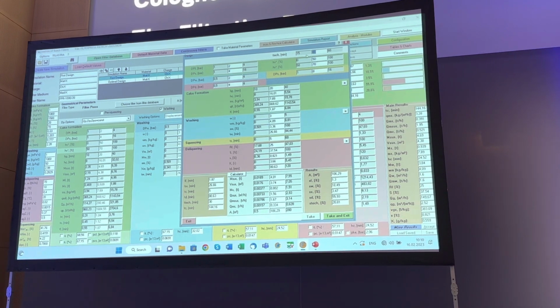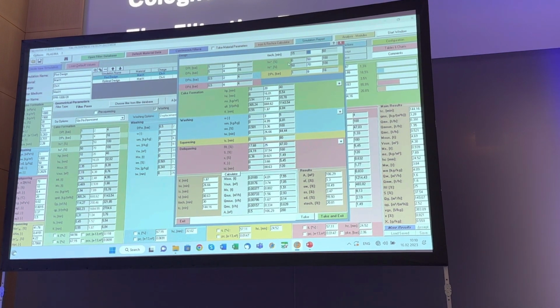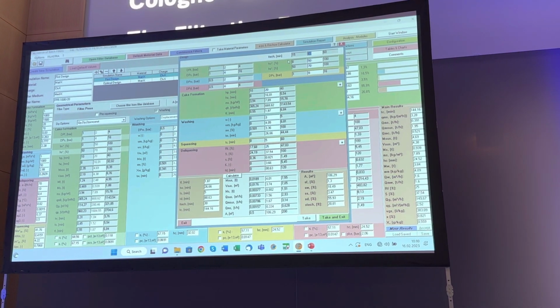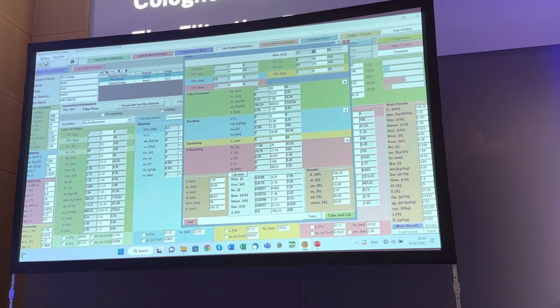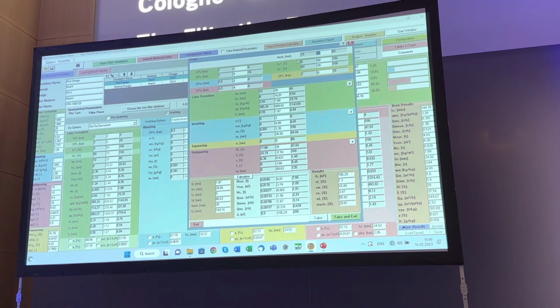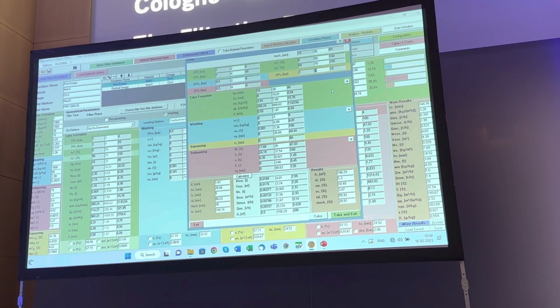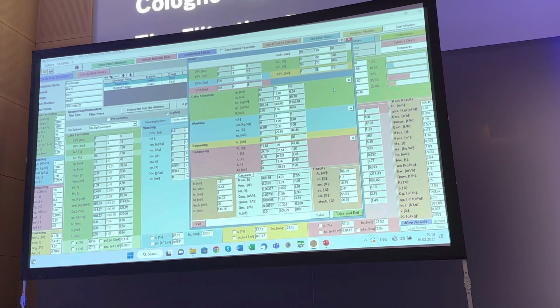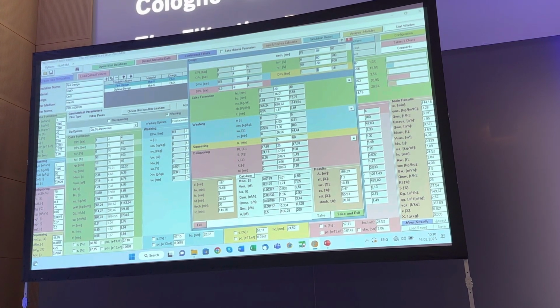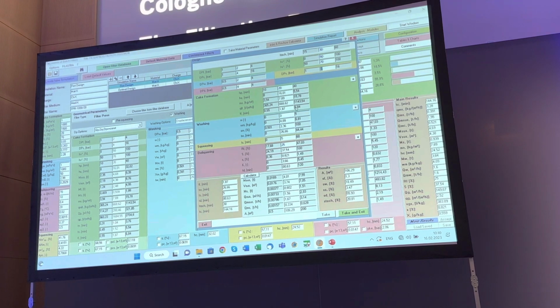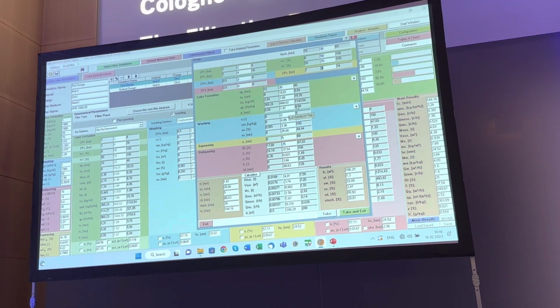Then we assume a technical time of 30 minutes. It is the time component not belonging to formation, washing, squeezing, delivery of the cycle time. And we assume we squeeze the cake after washing with 8 bar. Now you see the program calculates, you see these min and max values. That means what is possible.